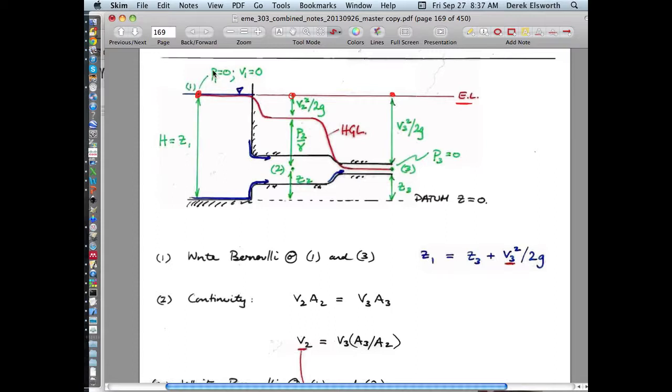There's no pressure in the system, no pressure potential. There's no velocity. As you go downstream, you've taken this fluid from being stagnant and you've accelerated it, so you've applied some velocity. So a portion of it is now kinetic energy, and a portion of it is this hydraulic head, which is the sum of elevation of the point and the fluid pressure that you'd feel at that point if you're sitting at point 2.